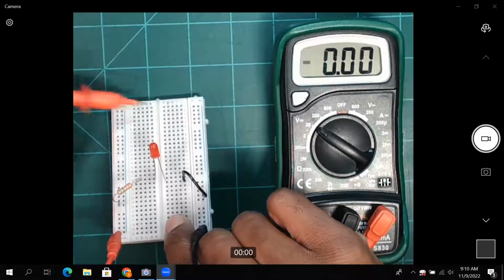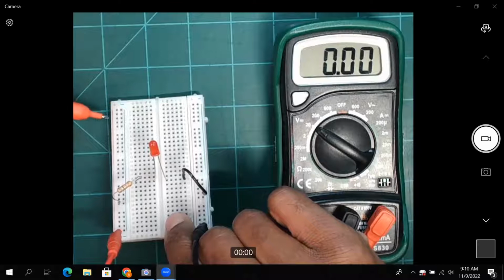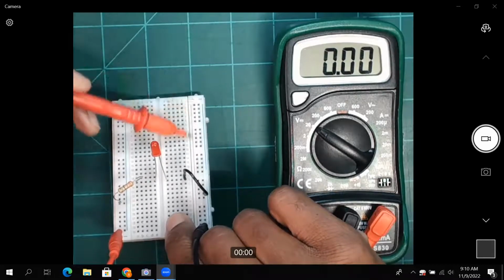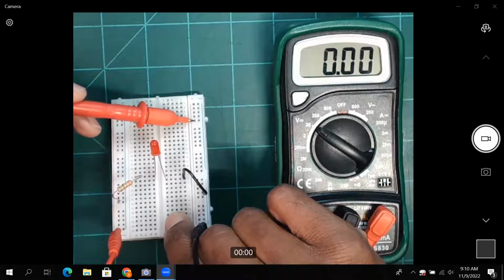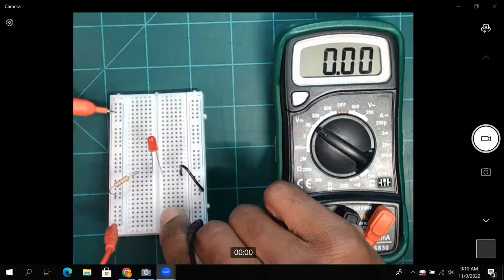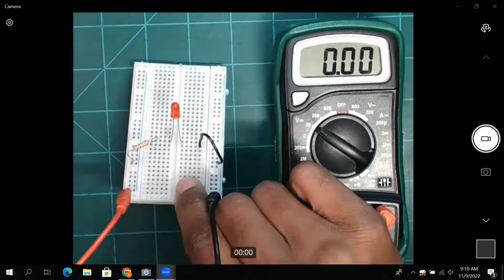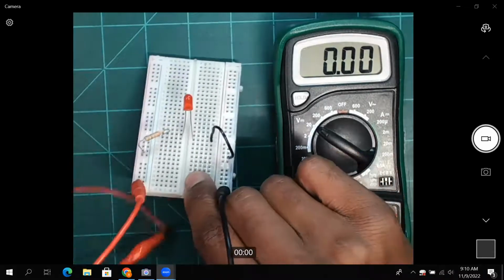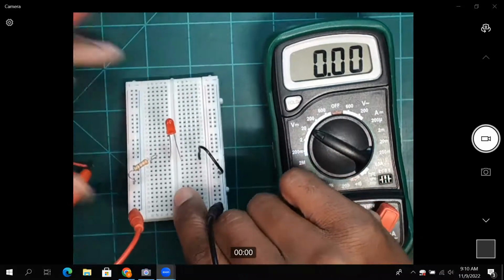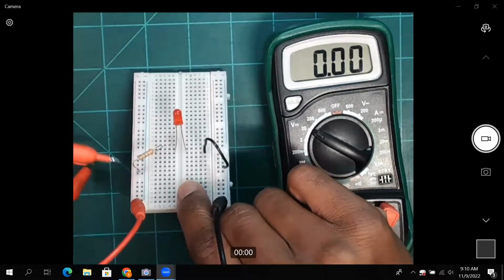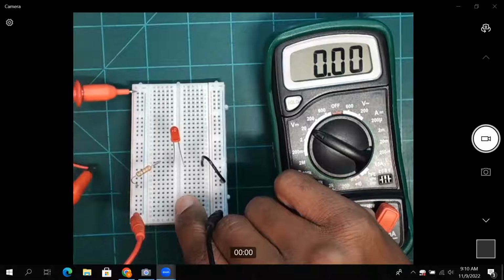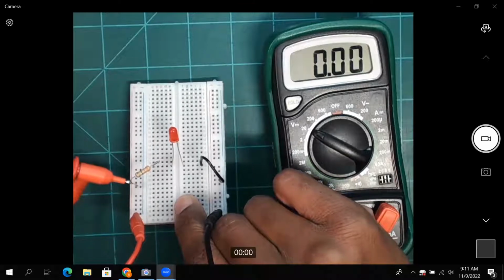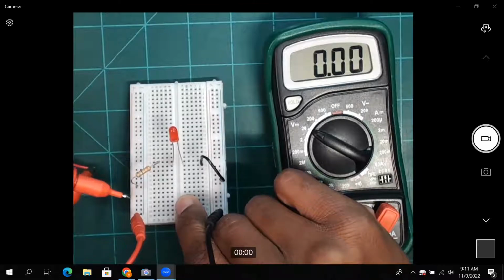Over on the side of the breadboard, you have a positive end and a negative end. On the left side, a positive row, as well as a negative row column, that is also connected to the breadboard on the right side. These connections are all one connection. If you see how I have my 9-volt battery right here, my positive lead of my battery is connected to the positive portion of my breadboard. That means this whole row right here is live. So anything I plug in to the positive row, that's where the positive current is going to flow through, right?